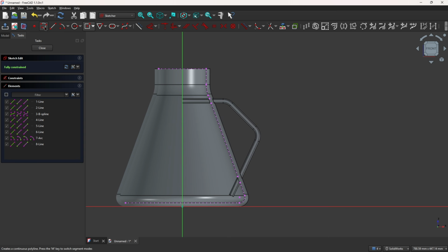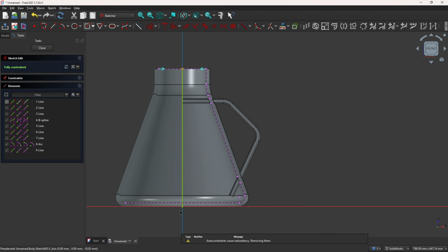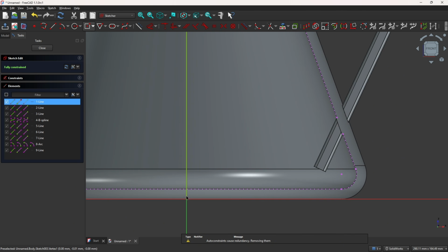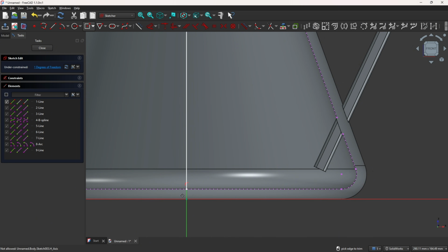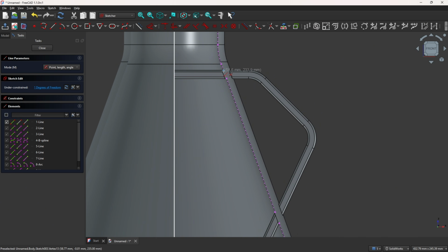And now select a line, make a line here from this point to this point here. This line here, let me cut here. Make this line or this point here horizontal with this point. So go to horizontal vertical, select this point and this point here. And select a line, make a line between these 2 points and make a line between these 2 points.